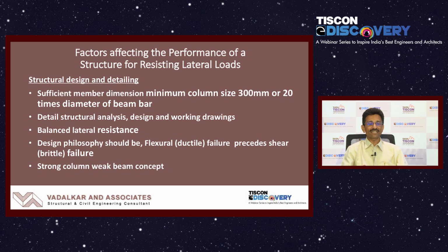So the design philosophy as far as earthquake resistant structures are concerned is basically the strong column and weak beam concept. The column should not fail. If the beam fails in flexure, that is desirable, as that will form a plastic hinge there, but the structure will not collapse. So this philosophy we must adopt now in our designs.